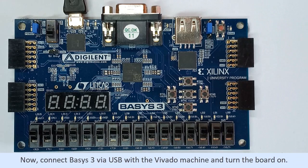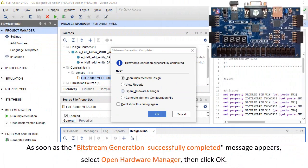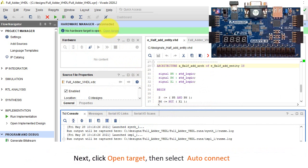Now connect Basys 3 via USB with the Vivado machine and turn the board on. As soon as the bitstream generation successfully completed message appears, select Open Hardware Manager, then click OK. Next, click Open Target, then select Auto Connect.